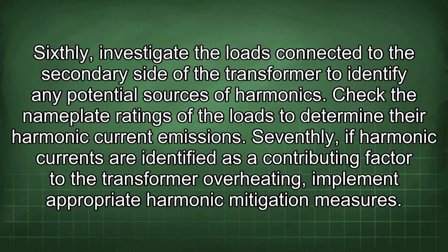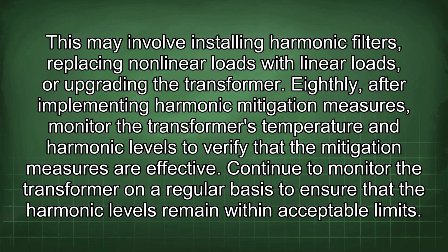Seventhly, if harmonic currents are identified as a contributing factor to the transformer overheating, implement appropriate harmonic mitigation measures. This may involve installing harmonic filters, replacing nonlinear loads with linear loads, or upgrading the transformer.